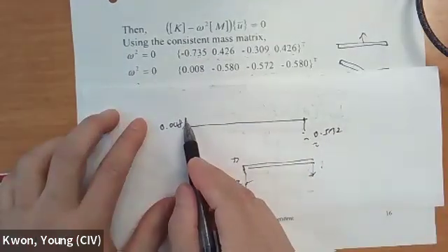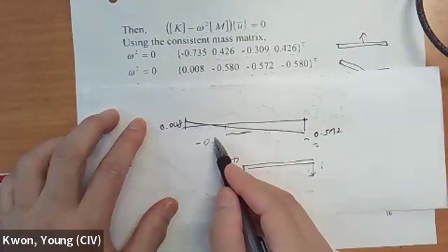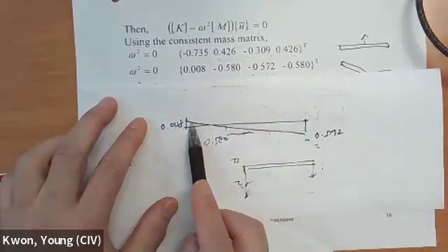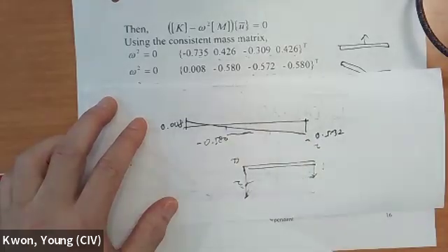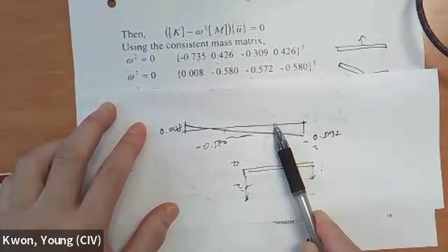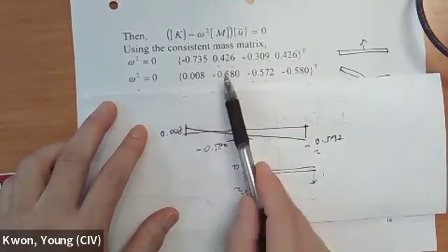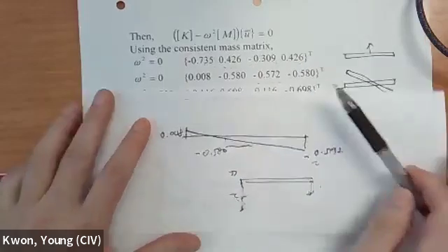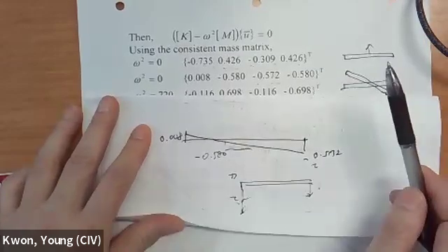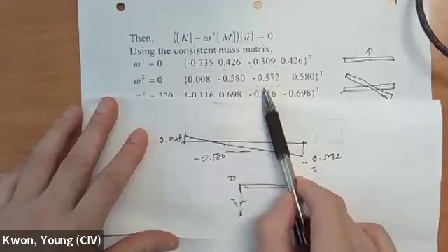Okay, and then if you look at the slope, this is going to be negative 0.580. So again, this is another rigid body motion, but a combination of linear and rotational rigid body motion. Make sense? So both zeros indicate rigid body motion, but the mode shape somehow indicates a combination of the two rather than two individual separations. Okay, because with the zero value it is almost impossible to separate this out.